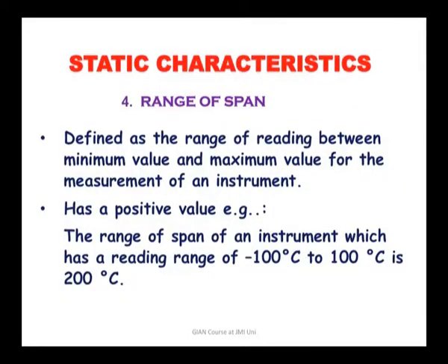Now we'll take a few terms of the static characteristics. Okay? So one of the terms used is tolerance. So tolerance is like how much you can tolerate, isn't it? It's very similar for the instrument: how much you can allow your instrument to give error. If you think of percentage, percentage may not be appropriate, because percentage changes with your range. But in some situations, you actually rely on the absolute value.